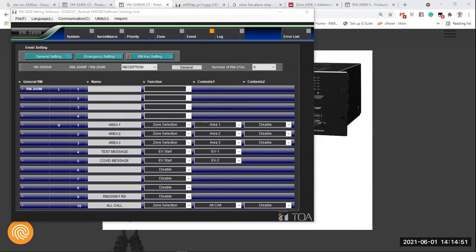Your messages must not be MP2, MP3 files. It only accepts WAV or wave files. These wave files, when you are converting them, you must convert them at 48 kilohertz sampling frequency, and they must not be stereo. It must not be a left and a right channel. It must be a mono output, one output. So not stereo, but monaural.